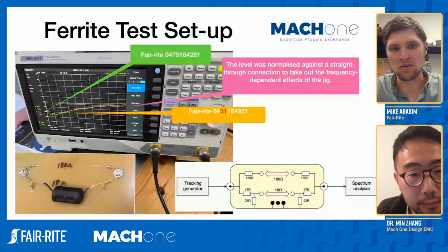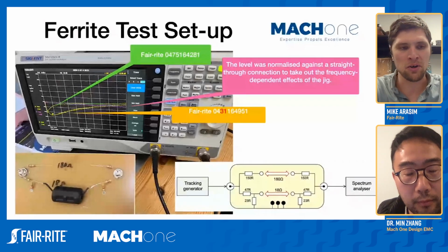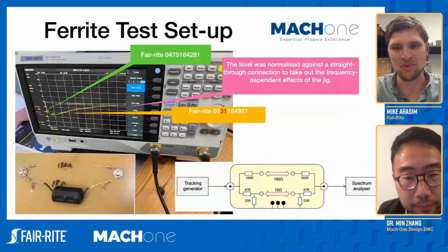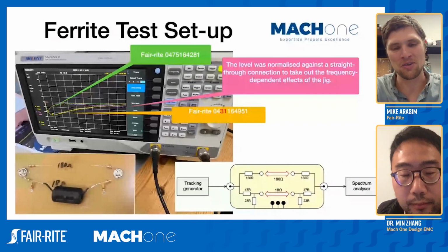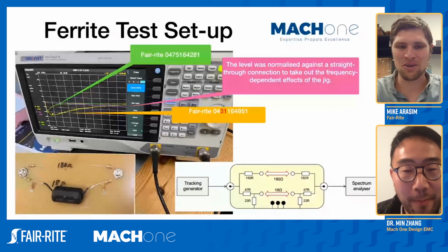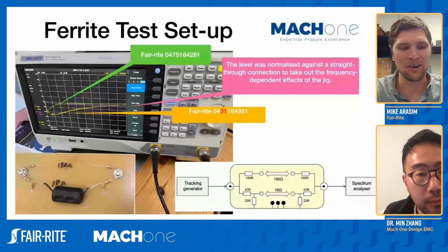And in terms of conductor, it's important that we keep the same conductor diameter consistent from part to part. And the wire length, we keep as short as we practically can, because ultimately you could put a pretty long piece of wire and it really looks like a pretty good ferrite when you're looking at it on an impedance analyzer. Exactly. So we try to minimize that to keep the measurement of the ferrite.